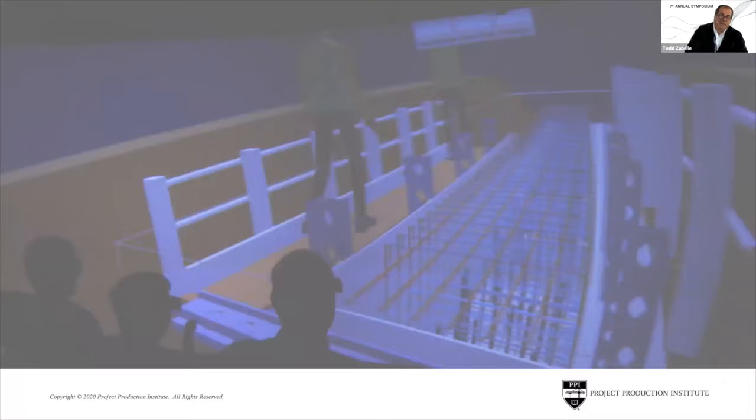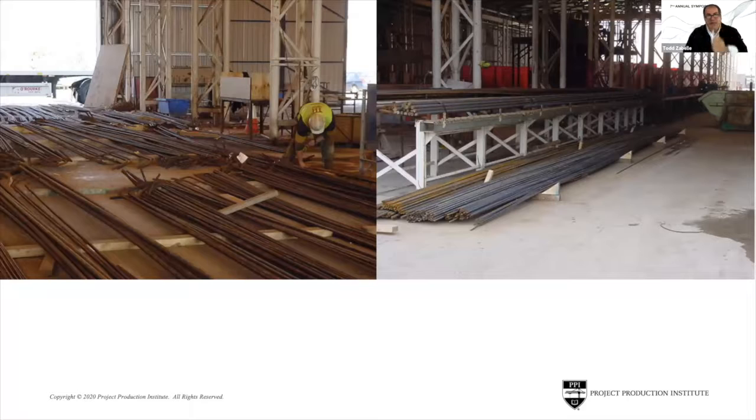And to be able to get to that level of detailed engineering so fast, standards were set up as a platform, if you will, on the modularization as a design requirement for the structural steel, and then the fixers were brought in early using immersive reality to figure out, can we or can we not do that work?